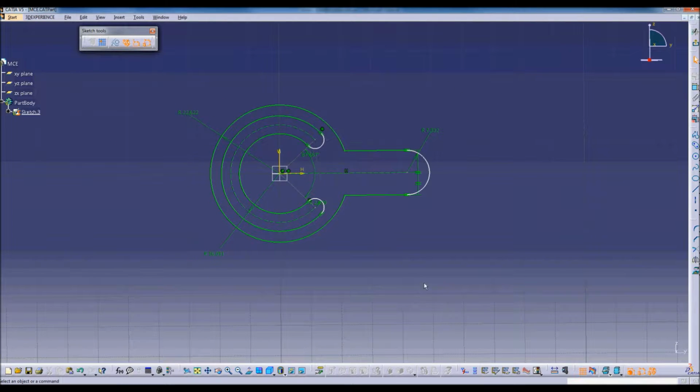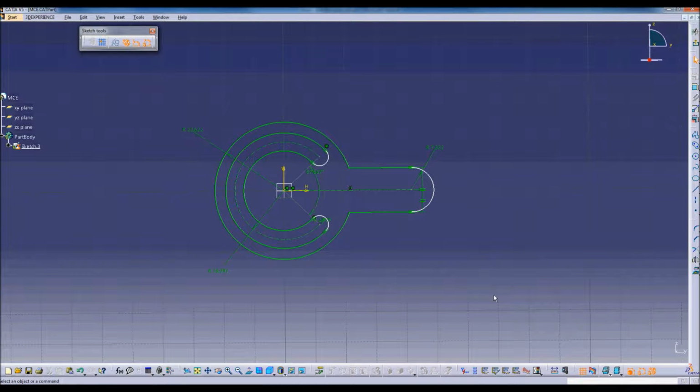It's also worth noting that since we're using R26 in this case, the automatic constraint option is on in Sketch Tools, and we create considerably more dimensions than previously. We can also analyze the curvature of curves using the porcupine analysis.